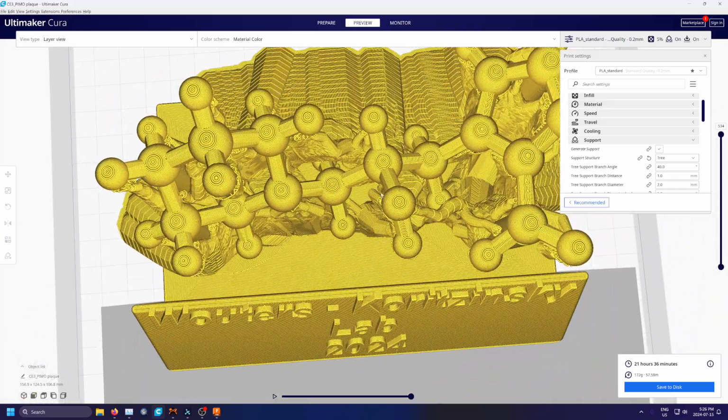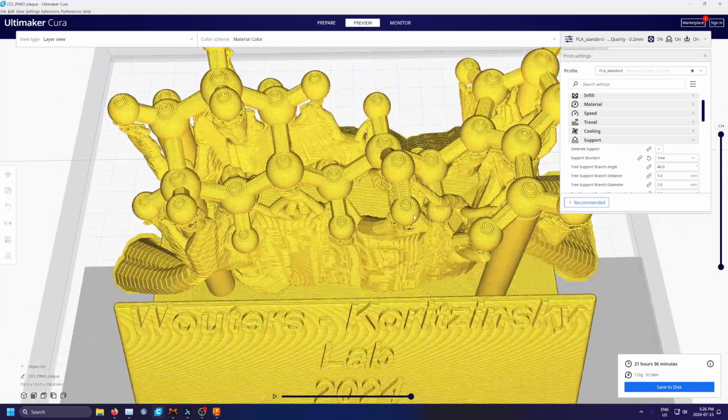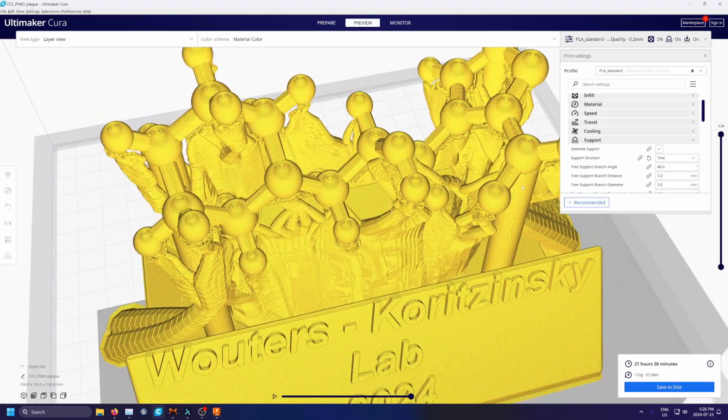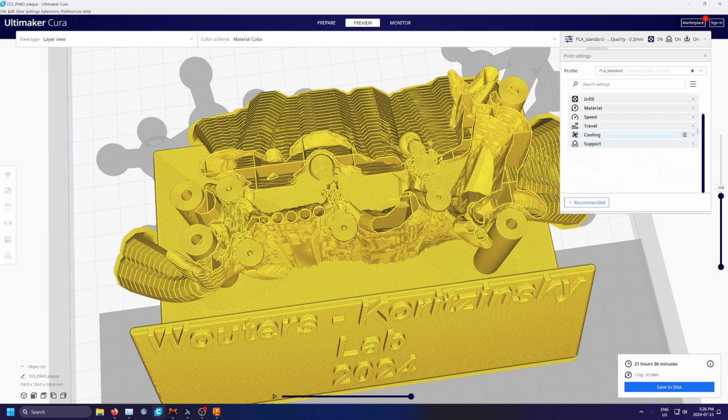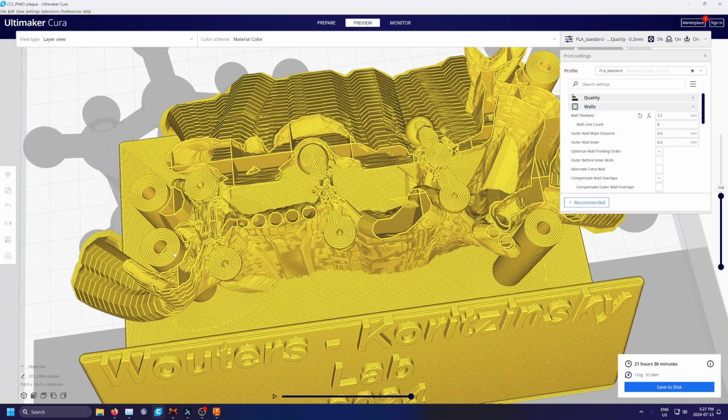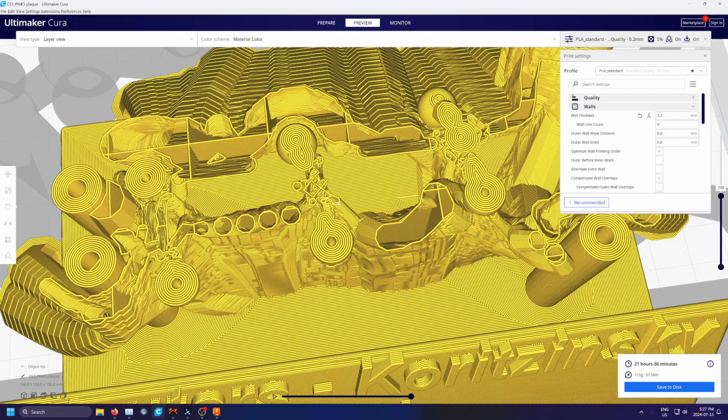Another sort of design consideration was structural integrity. I will be removing these supports, except for the permanent ones, and when you try and remove supports, sometimes the support might also take away a part of the model itself. So you want to make sure your model is quite strong, durable, and rigid. Most people would set an infill of 100% and call it a day. But in reality, you don't really have to do that. In fact, adding more walls or thicker wall count can account for this.